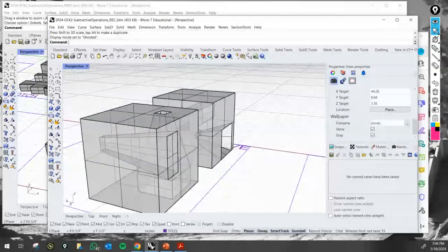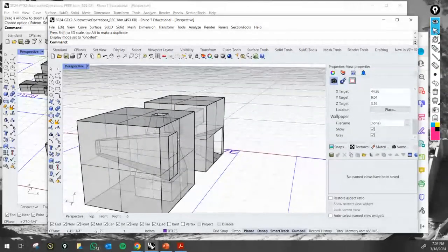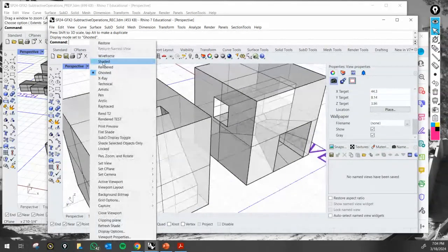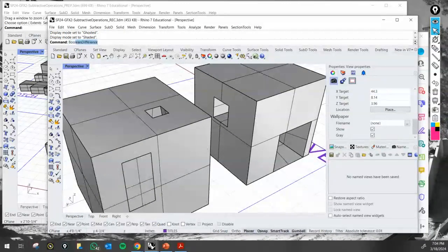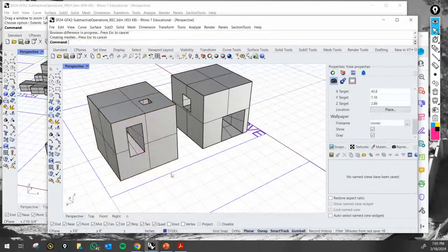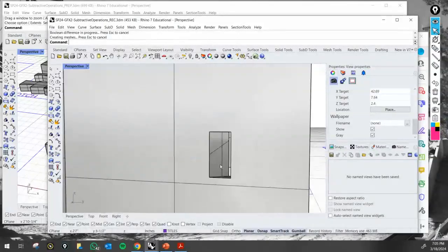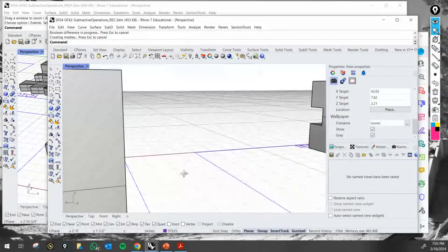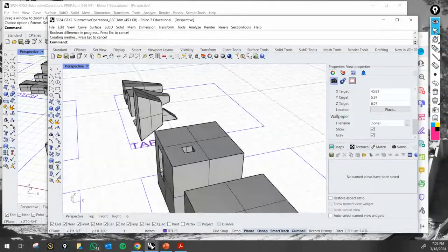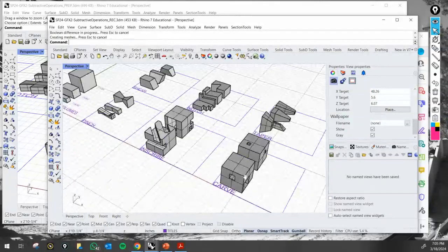Again, for right now, that's what our assignment is going to be: overlapping and creating larger openings and getting it a little bit more exciting. But for right now, just understand the simple concepts: Boolean difference, select the object, enter, subtract with that one, enter, and we have carved those openings here. They run from one end to the other end.